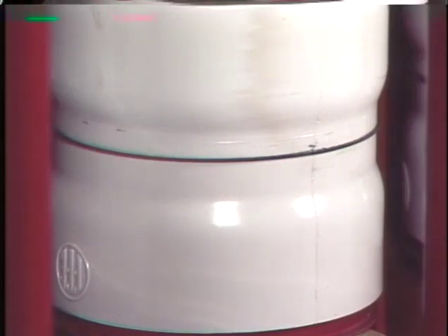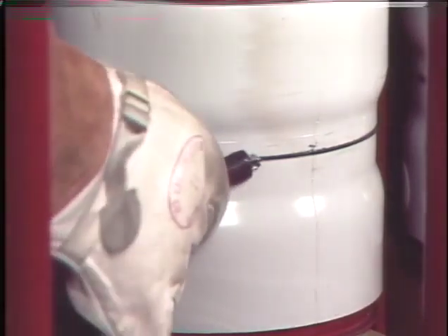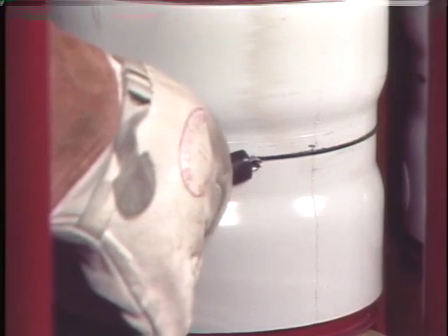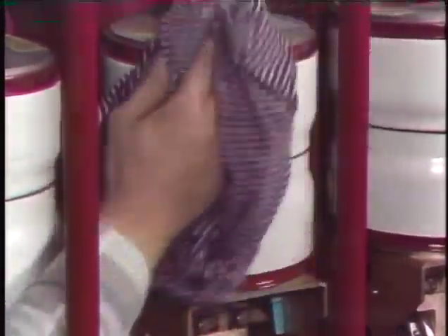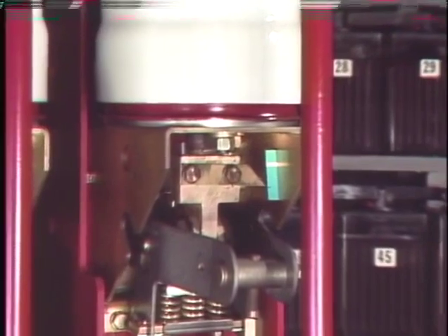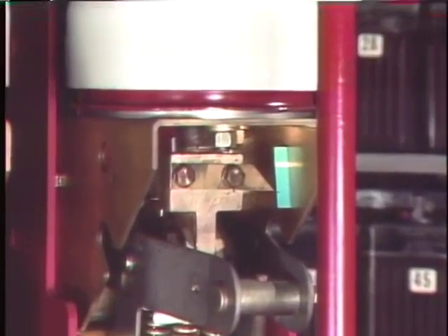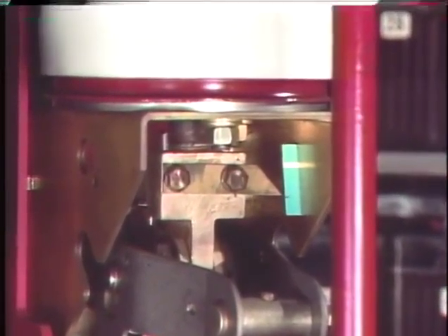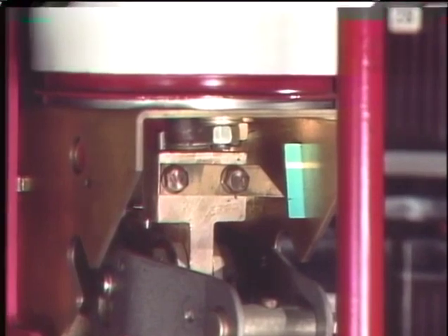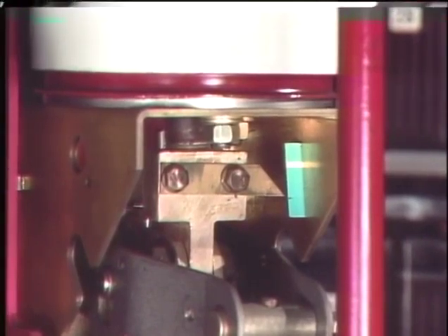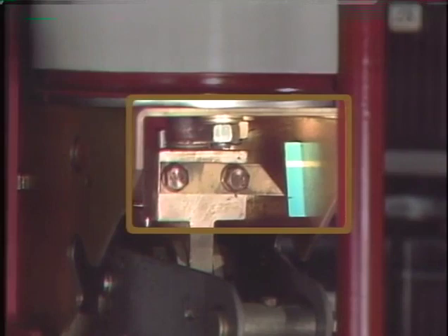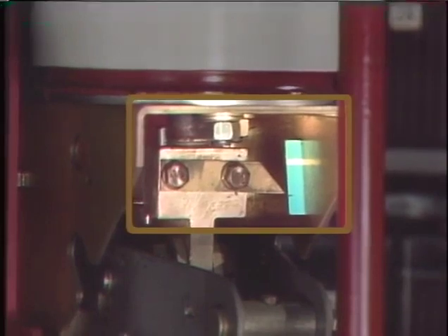Before work begins on the vacuum breaker, the rings should be shorted to ground to safely discharge any charge on the ring. Then the vacuum bottles can be cleaned with a dry, lint-free rag. Checking the contacts on a vacuum breaker is different from checking the contacts on other breakers because they're sealed in vacuum bottles. Instead, an erosion indicator is provided for the contacts in each bottle.